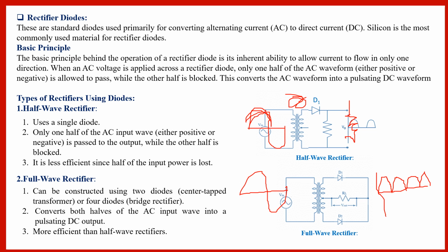As a result, this rectifier is more efficient in comparison to the half wave rectifier, and the amount of ripples is also lesser here if we compare full wave rectification with half wave rectification. Similarly, we may say that diode D1 is conducting at this particular point, D2 will be conducting for this, then again D1, then again D2, and this cycle will go on like that.